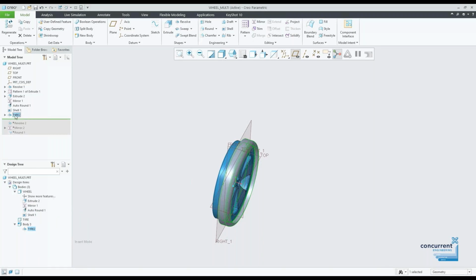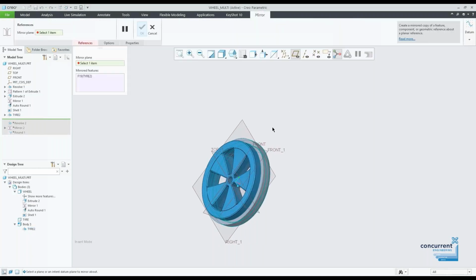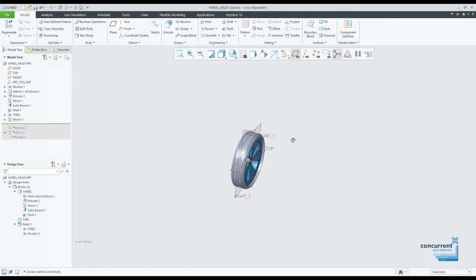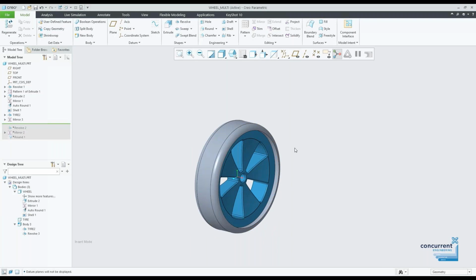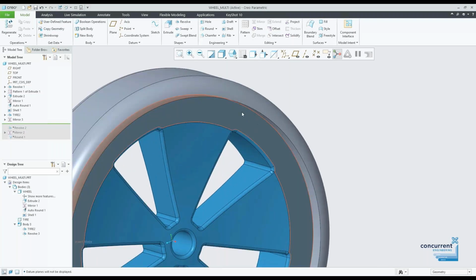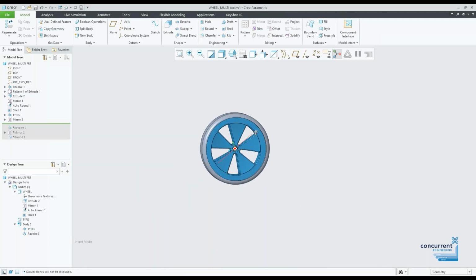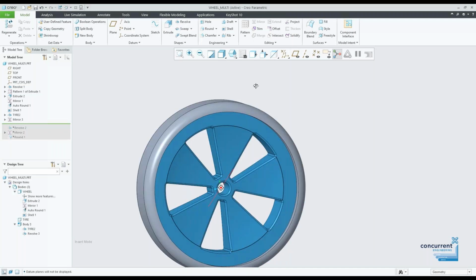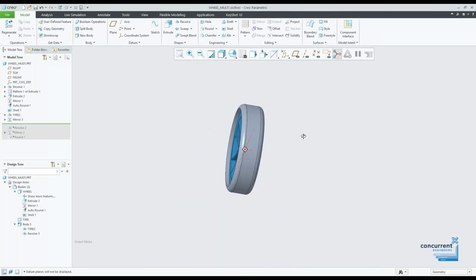Okay, and simply with tyre 2 selected there or here, we can mirror in itself and create this nice tyre. Now what this gives us is the ability to essentially make sure that the geometry is absolutely correct. So the existing wheel, which we would require as a reference so the tyre snapped nicely around it, would be more difficult to do with separate parts. As I said earlier, you'd have to remember the specific geometry of it. But this allows us to basically design in context.